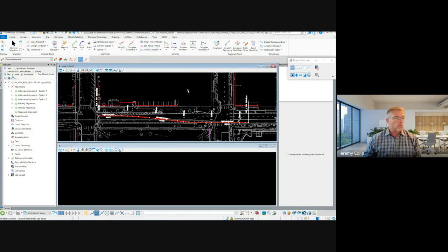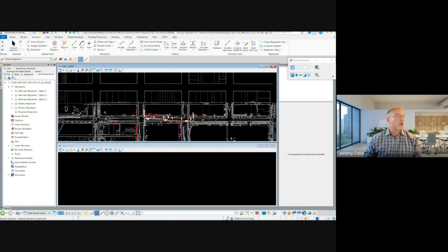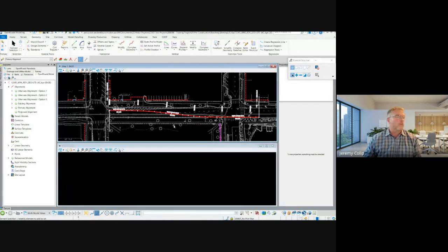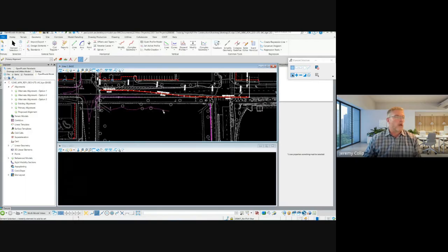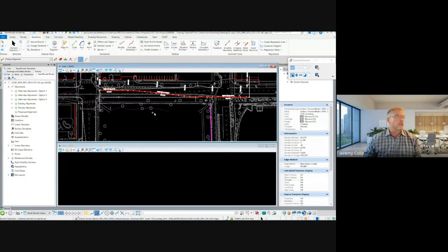So in order for me first to create a profile, I need to make sure that the terrain I have in my file itself is active. And as you can see right here, by this button here, I just made it inactive. So you can see set active as terrain model. So it now knows that it is an active terrain. It'll tell me it's an active terrain.